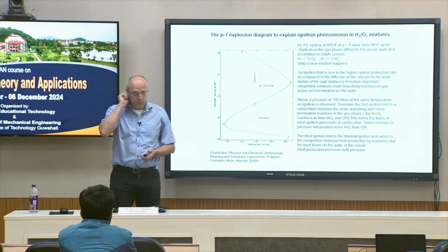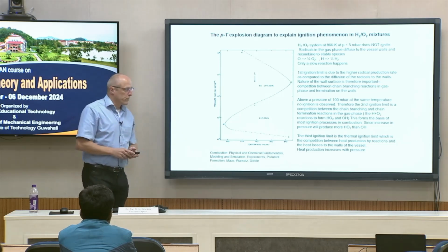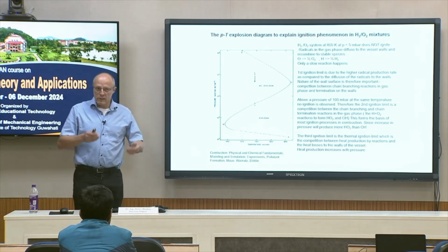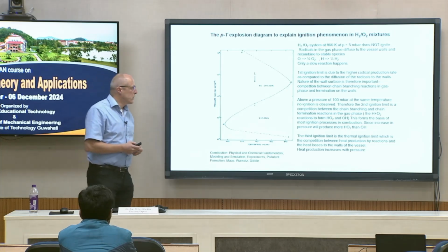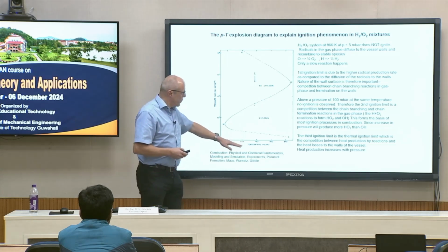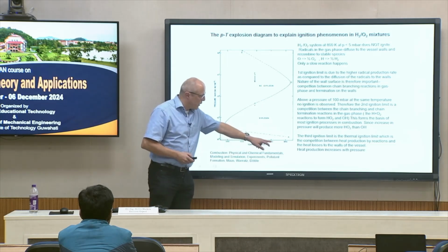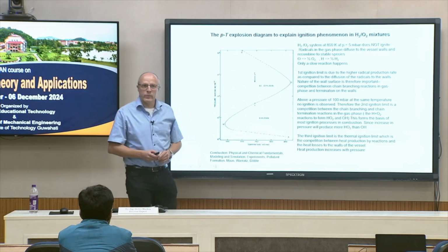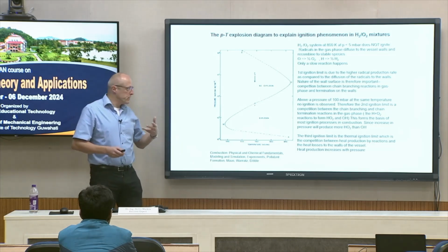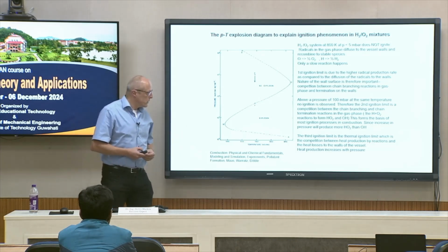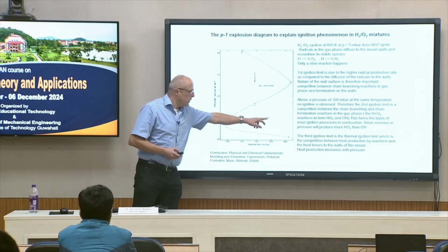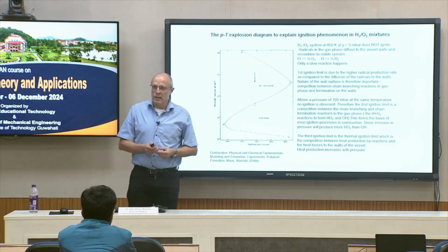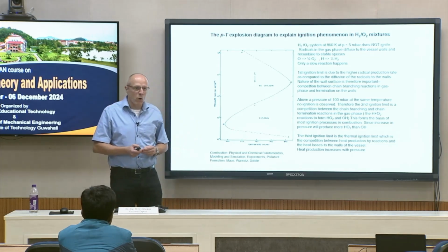And this is very typical, and for most of the combustibles you see a similar result, of course, at different pressures and temperatures. But you see that if you sit on a specific temperature, here for example 800, and you increase the pressure, you start with no ignition at low pressures, then you come to an ignition region, and again at higher pressures suddenly it does not ignite anymore.